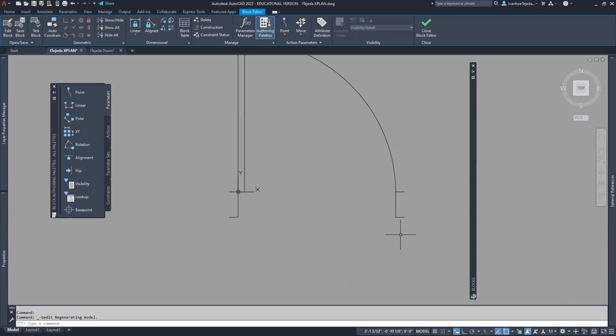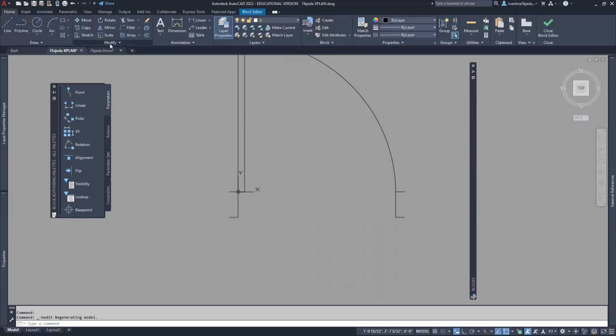So what I will do is stretch it. Now, where's the stretch command? It's hiding. I'll go back home here to the modify tab, and there's stretch. When I do a stretch, it tells me to select objects to stretch by a crossing window or a crossing polygon. And I know that a crossing window needs to go from right to left. So I know I want to stretch these 2 endpoints here and there. So I will simply click here, let it stretch over that way, click, enter, and then stretch this from a point anywhere that I would like to pick.